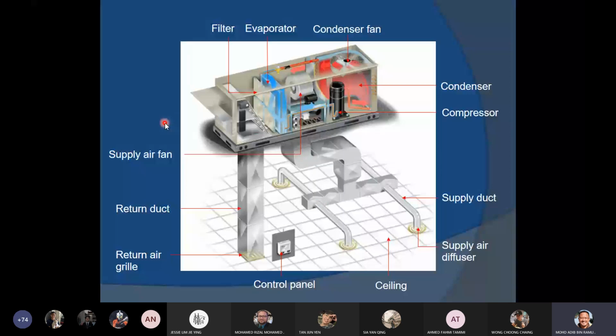As the air enters the package unit, it basically gets filtered. The fresh air from outside, like I mentioned, is not so fresh, it's kind of polluted also, right? With smoke and other pollutants. So it gets filtered, and then it passes through the evaporator, which is the cooling coil, and becomes cool.